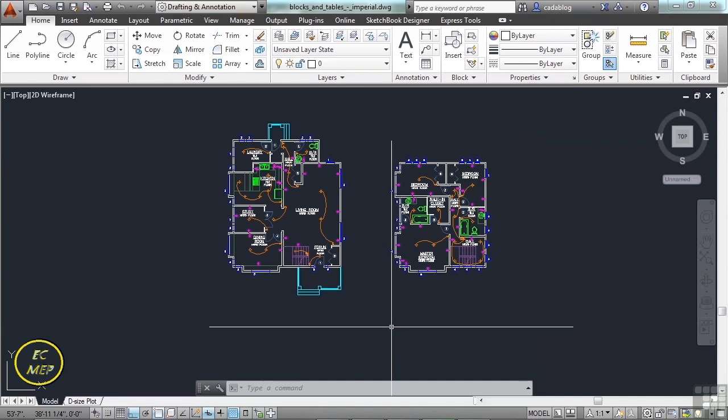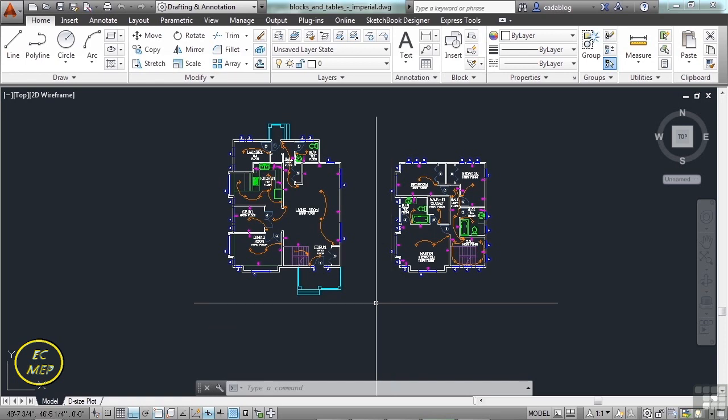There are several different ways and methods that you can list out the properties of the data or line work in your file. One way is to use the properties palette, as we've seen in other chapters already. That's great for one object at a time, but it can be overwhelming because the amount of information the properties palette shows you is, well, everything. So there is a feature that you can use that's called Quick Properties. This feature will pop up a window that will display a very short list of properties for the object you've selected. This feature can get annoying though as you progress in AutoCAD, and if you're working with more complicated drawings, then it can really get in the way.